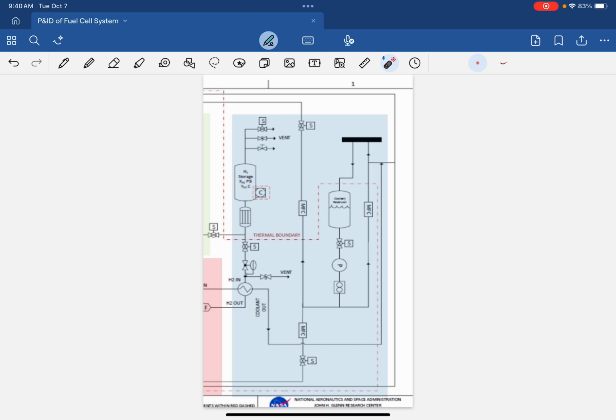We'll go this way following this pipe, and the hydrogen can either go up or down. It all depends on this other solenoid actuated ball valve. Let's say this is closed, so the hydrogen will go up here. This is an ice catcher. With the hydrogen being so cold at this section, it can produce ice, and if there's ice or solids in the product that's flowing, it's not going to flow very well. So this catches all the ice and allows the hydrogen to go into this vessel that's holding hydrogen at a specific pressure and temperature.